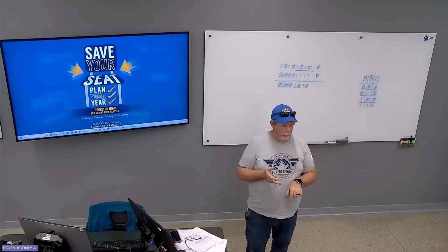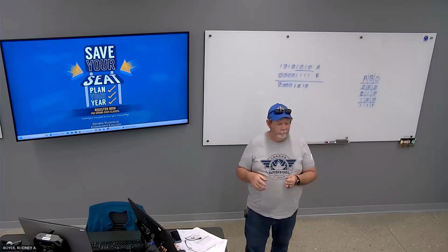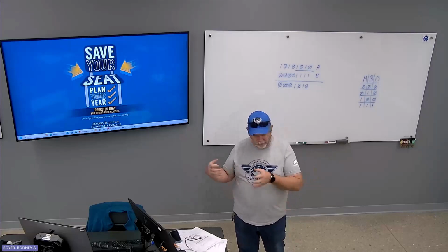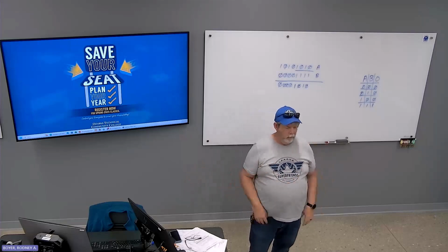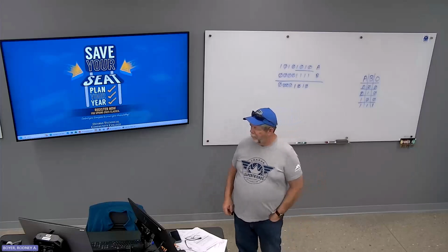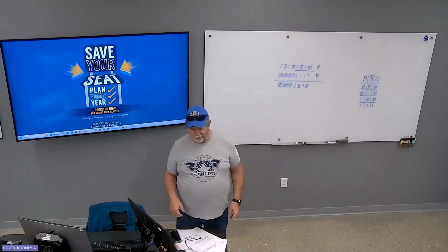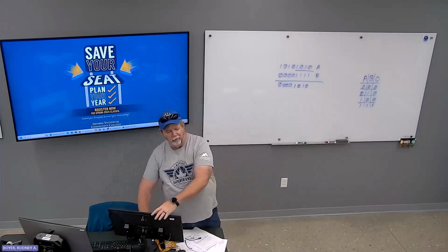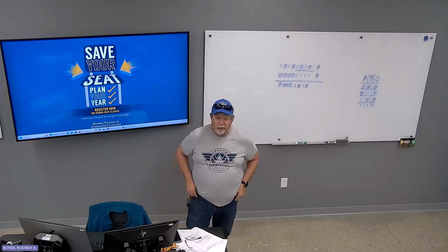Clamp, blend, decel, position, stop, unclamp. Then take that bin off, put a new one in, clamp, blend, and so on. They don't program the machines with sequencers, but they could easily do that and simplify the logic quite a bit.